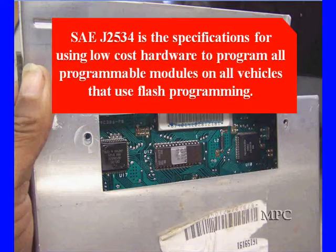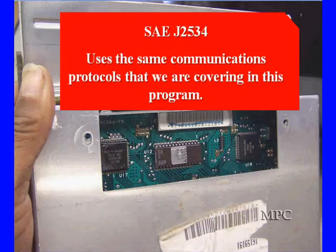You use J2534. It's the specification for using low-cost hardware to program all programmable modules on all vehicles that use flash programming. Let me say that again. You can get low-cost hardware that plugs between a personal computer hooked to the manufacturer's internet connection, and you can program all the modules on all the cars using flash programming. Now, that's required by the EPA. This is here so you can do it. But if you're going to replace modules, you need to be doing programming. It uses the same communications protocols to do this flash programming that we're going to be covering in this program.